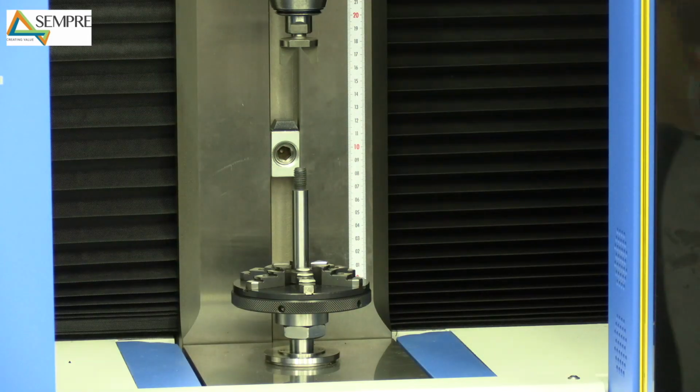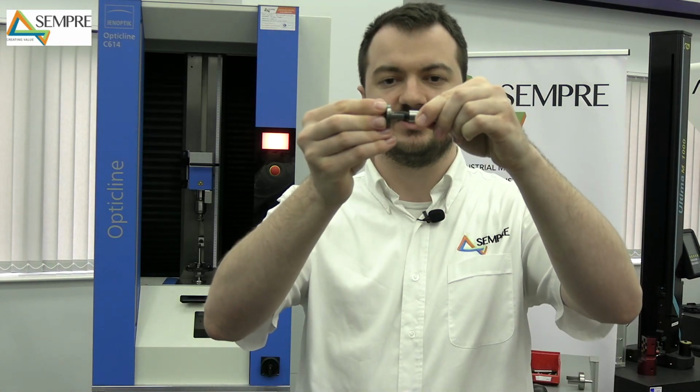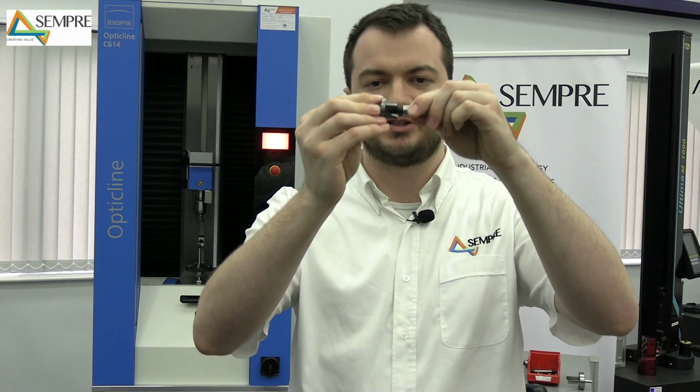but you may notice, and I'm just going to grab our other one, that when we load it in, you can see how much that obscures the part. So it's obscured so much of the thread that at certain angles you just can't see the thread at all. And when you need to do a rotational feature like a run out, this can obscure so much of it that you can't do that measurement. And therefore, instead of that, we've used a chuck.